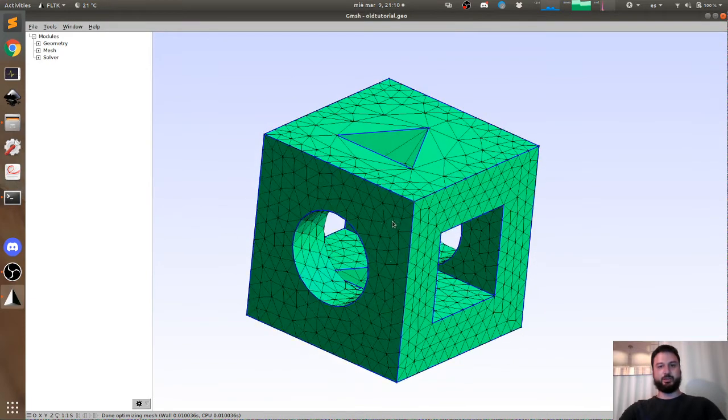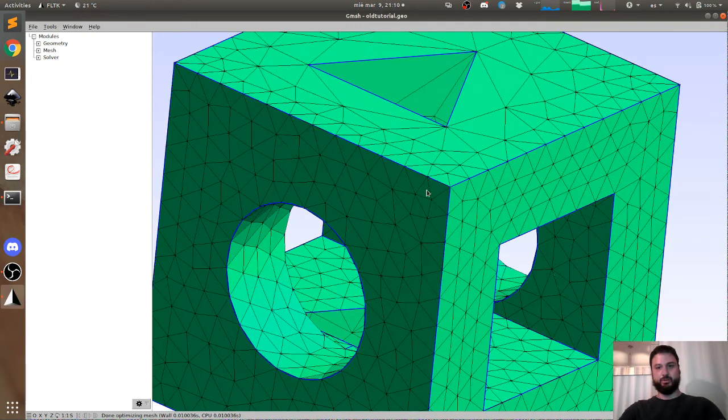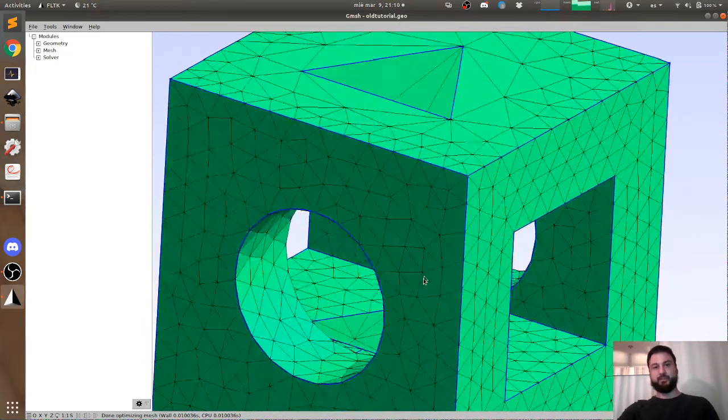The finite elements are these triangles that look like this, but they're actually tetrahedrons. So you can imagine that these are pyramids, or triangular base pyramids. That is, they're defined by 4 nodes. They're tetrahedrons. So the way we subdivide this shape into tetrahedrons from the geometry is called the meshing or the discretization, numerical discretization of the geometry. So two concepts, geometry and the mesh of the geometry, are separate.